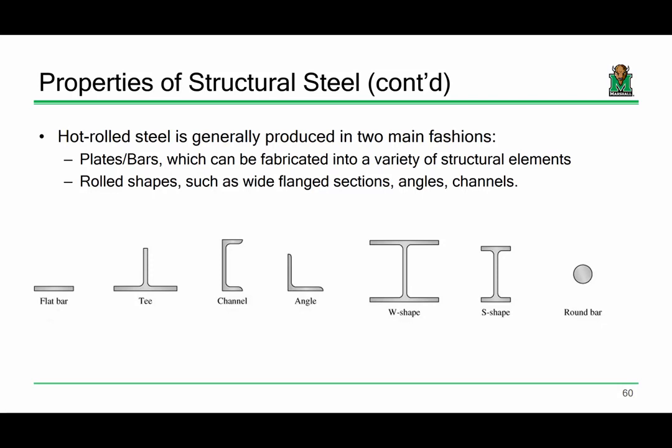In bridges, when we're using piles, let's say for abutments, for the foundation at the end of an abutment, we actually place those in weak axis bending. So instead of facing it like an I, we face it like an H. There's a reason for that: under thermal conditions and movement of the ground, we'd like the abutment to be a little bit more flexible. So we place it in that H configuration. But if you're talking about a building, nowadays they're just using W shapes. If they want to call them I shapes or H shapes because they're looking at it this way or this way, I'd tell them just move here.